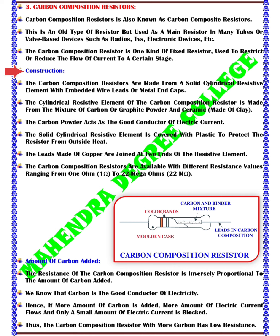We will see the construction of carbon composition resistors. The carbon composition resistors are made from a solid cylindrical resistive element with embedded wire leads or metal end caps. The cylindrical resistive element of the carbon composition resistor is made from the mixture of carbon or graphite powder and ceramic, meaning made of clay. Carbon composition resistors are made out of fine carbon particles mixed with clay. It becomes solid form after baking.